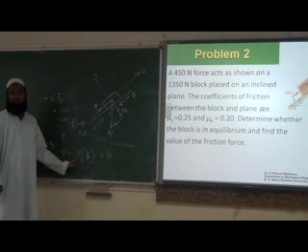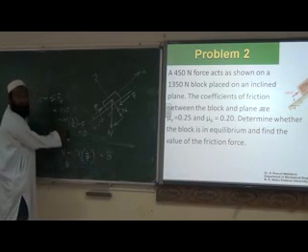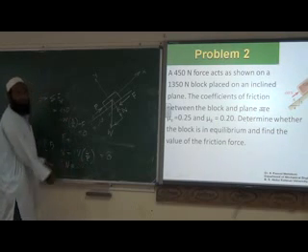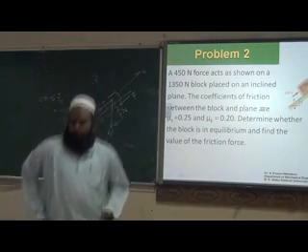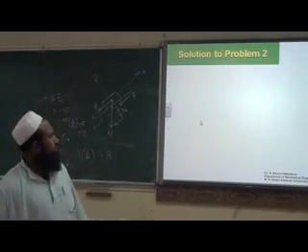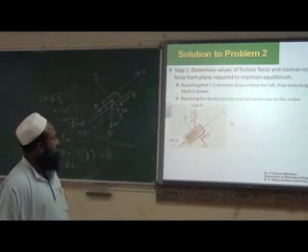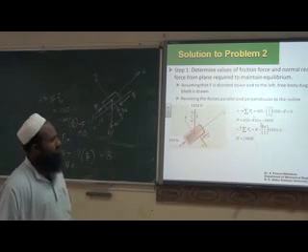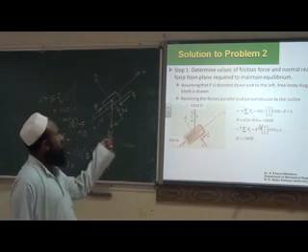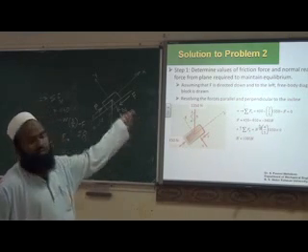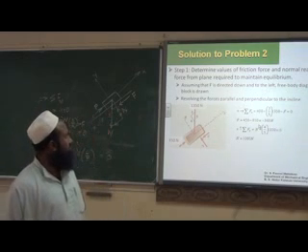Only two forces, N minus W 4 by 5, so you can find out N. You can find out F from the first equation, N from the second equation. F and N are found. Step 1: we have to find out the value of the frictional force and normal reaction, and check whether they are in equilibrium.